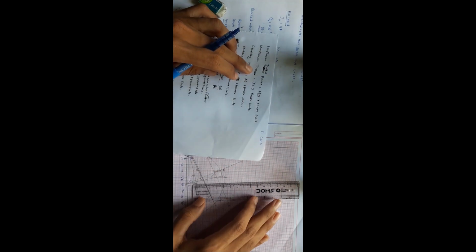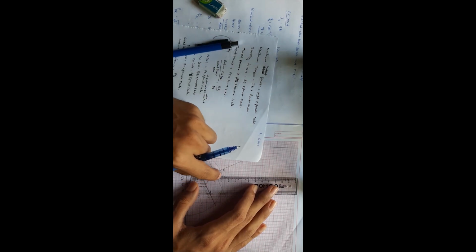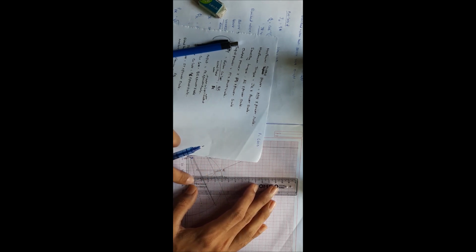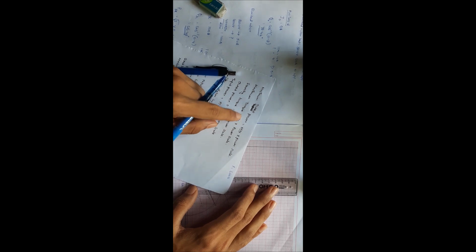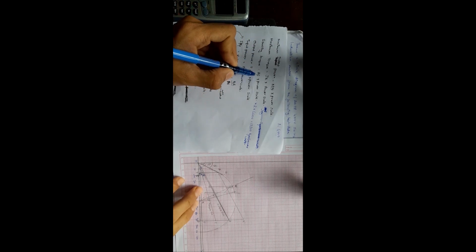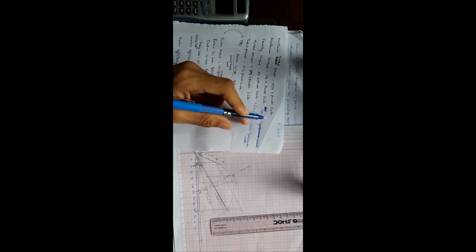Maximum torque will be from our torque line. From the torque line, the upper line where it intersects the circle, that is our J. From the torque line to J, we have to measure and take the torque value into the power scale. So here starting torque is AE, that is AE into the power scale, almost 2 centimeter. So 2 into 6600, the power scale, it will be 13,200 synchronous watts.